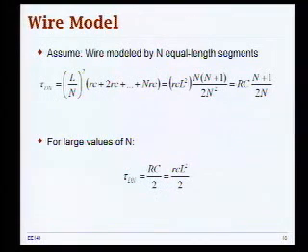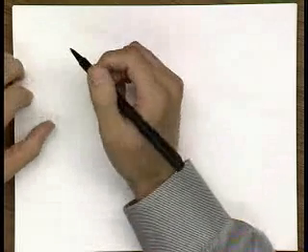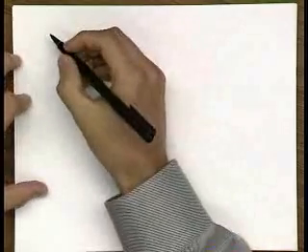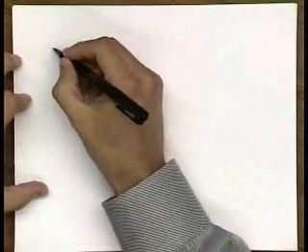This is basically how you come up with that expression of 0.38 RC. This is approximately 1/2, but when you do simulation, then you'll figure out that that's the number you're going to get. So let me now continue where we finished last time and do a couple of examples of this Elmore delay formula so you better understand what's going on, because that's a very important concept indeed.